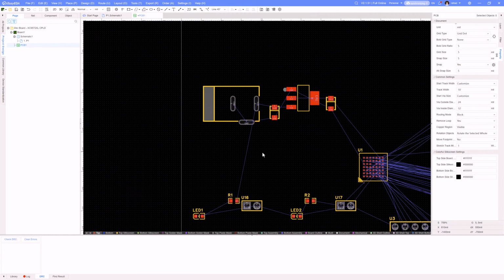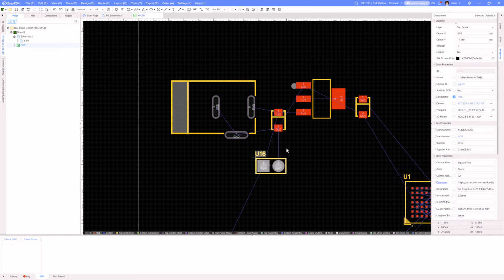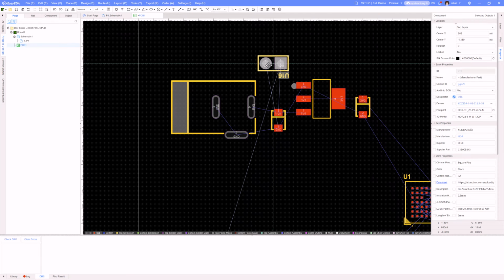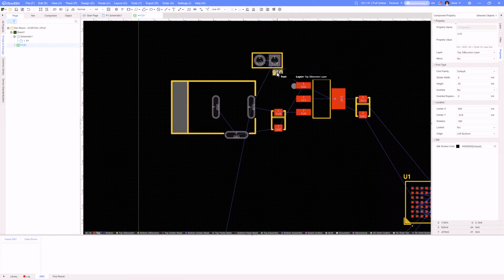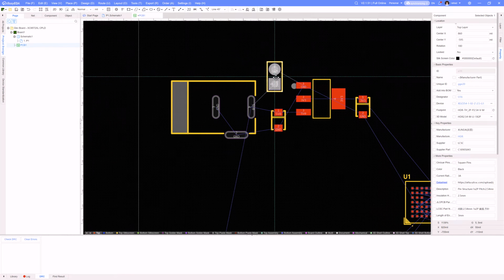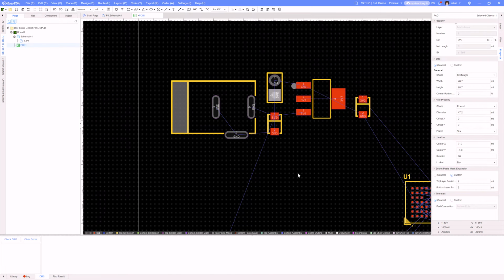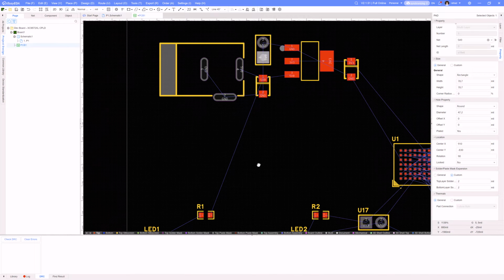And then I have a 5 volt header. So if I want to see what that looks like with my scope or meter or anything like that, I've got a nice little header I can work with. And I know I'm going to go with a 4 layer on this. So I'm just going to lay it out like this, and we'll come back and maybe this can be adjusted here in a little bit.